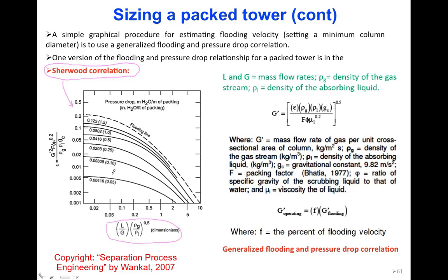And here I have pressure drop, which is in meter of water per meter of packing. Per each meter of packing, how many meters of water of pressure drop we have, or inside this parenthesis you have inch of water per foot of packing. Okay, so those are your pressure drop.